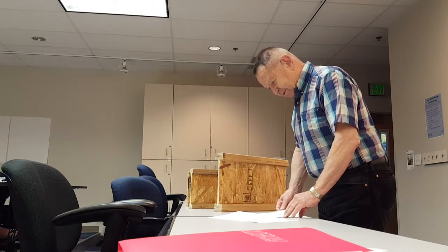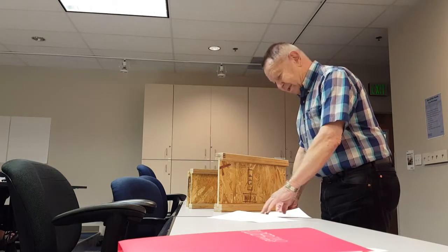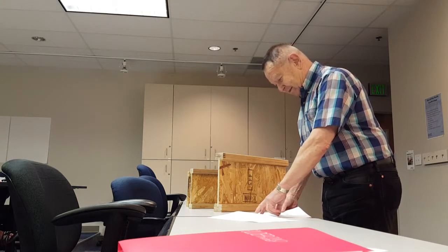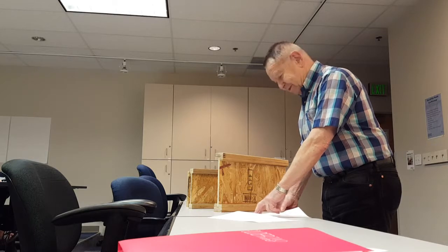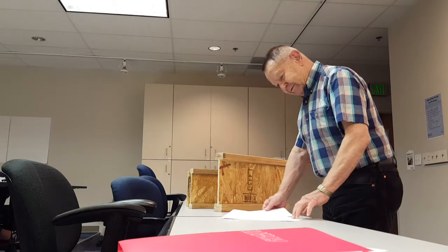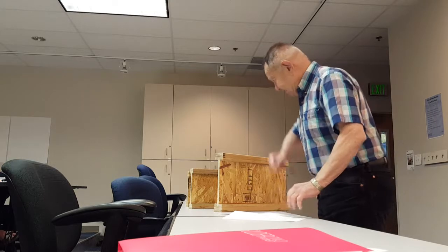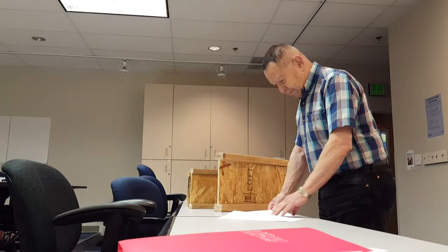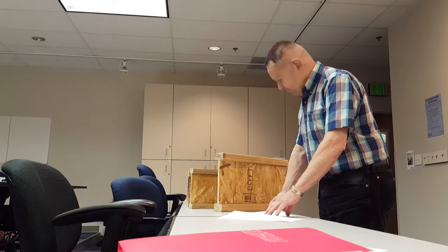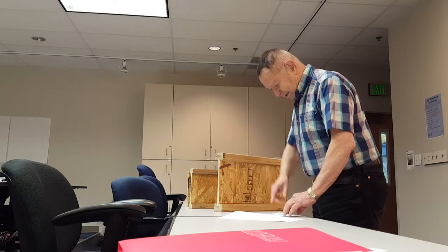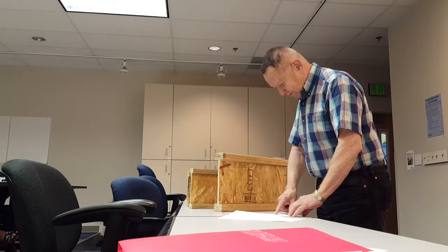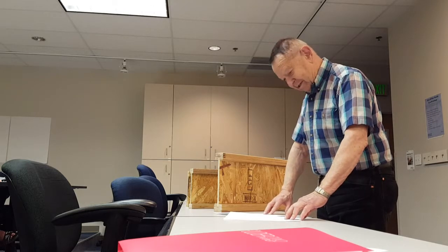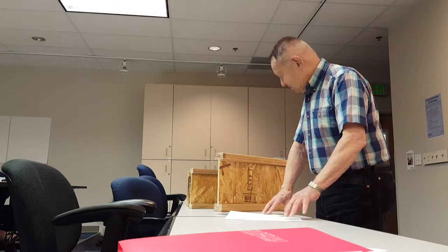And so then I also went ahead and did the comparison with 2x8. And you see, if you have 2x8 dimension lumber, your moment of inertia is less than the truss. And then for the heavier stuff, I think that's this one, I did the same sort of thing again, and your moment of inertia is 386 compared to the 237.